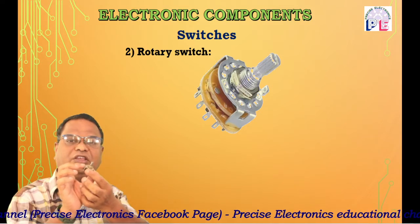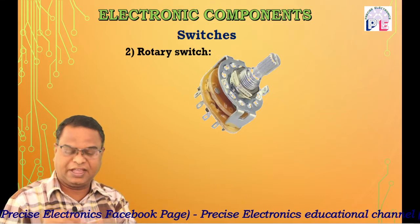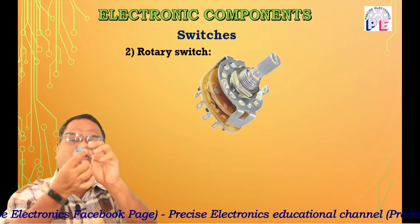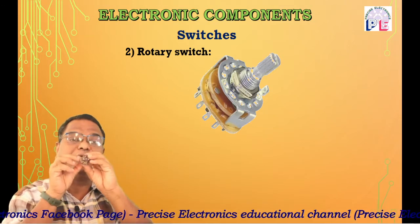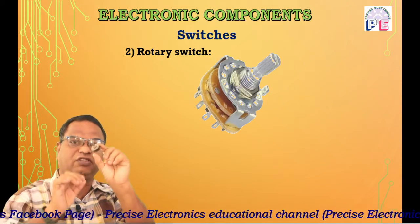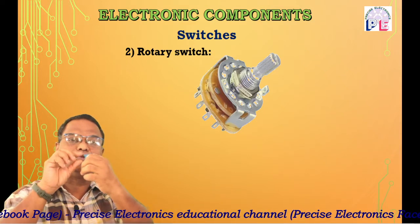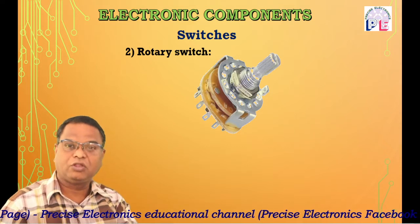This switch is mostly single pole, many way. This is a single pole 7-way switch, and this is a single pole 12-way switch. So there are different ways. By using this switch, we can control 7 circuits or 7 devices using this single switch, and by using this switch, we can control 12 different circuits. So this is the rotary switch.